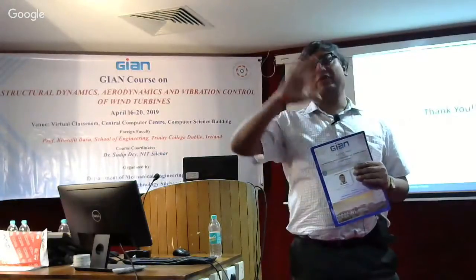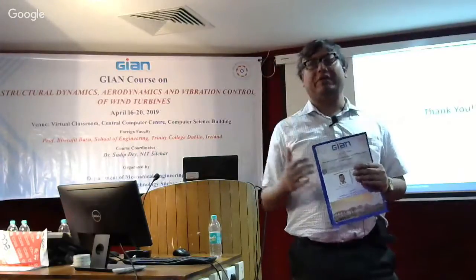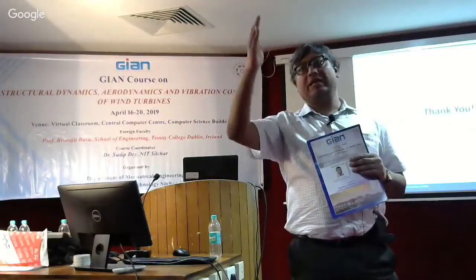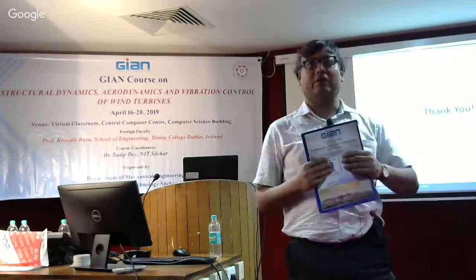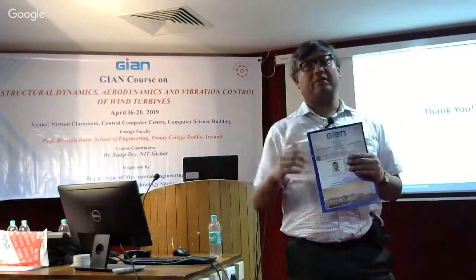Obviously, if you increase the wind speed, your load keeps on increasing. But if you change the angle of attack by changing the pitch, then you can change the load. So probably they're using some control there to keep that at a particular constant value.